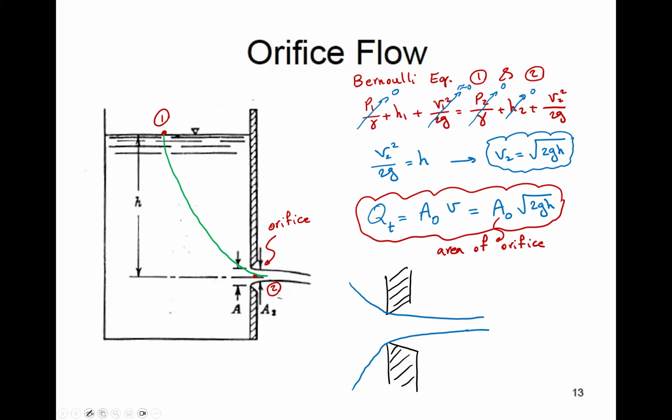So what is going on? If you notice, in reality, the size of the opening, I'm going to say area, but this is a section, so we know it's actually diameter, but for clarity, I'm just going to keep it as area. This is what the area of the orifice is. But in reality, that's not the cross-section of the flow. The flow area is actually this much. I'm going to call it actual area, which is slightly smaller than the orifice.